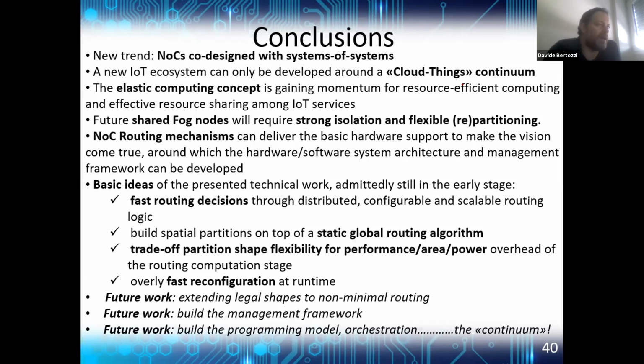So the point of LBDR is that it always tries to achieve minimal path routing, okay? That's its advantage, and that's its flexibility limit. Therefore, in case of U-shaped partition, it will tend to the destination, although there is a hole in the middle. And that's why we need to, for instance, introduce more configuration bits that allow the routing logic to take different decisions in case this is needed, such as the concept of the root bits.